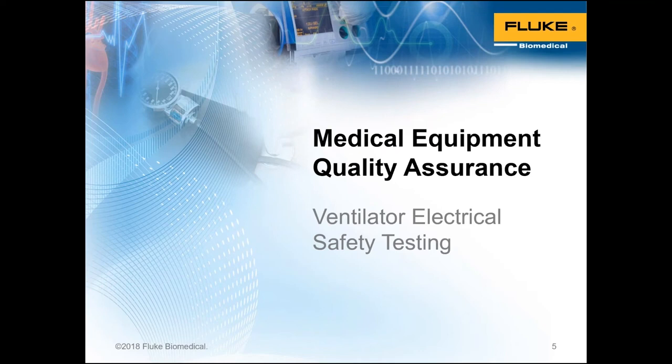And you'll remember that we're talking about doing electrical safety testing to comply with the IEC 62353 standard, which is a little different than, and somewhat fewer tests than, following the IEC 60601-1, which would be a requirement if you are a medical device manufacturer in your design validation testing, as well as in your final assembly testing in the factory. That would need IEC 60601-1.